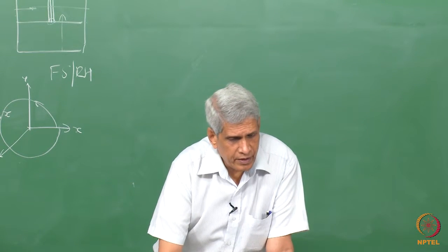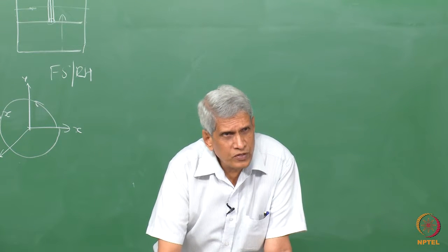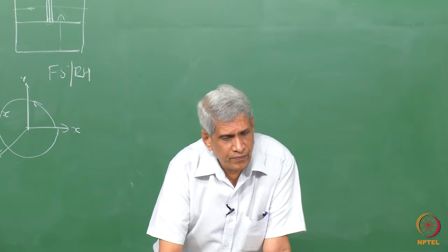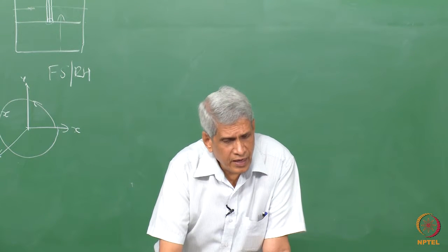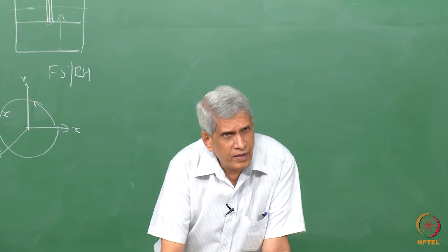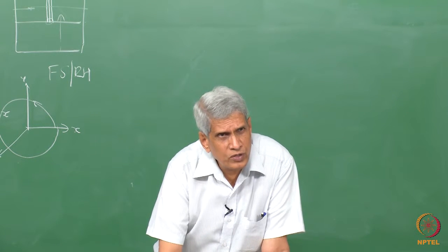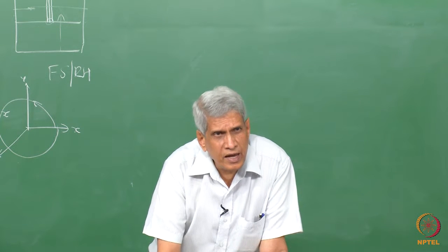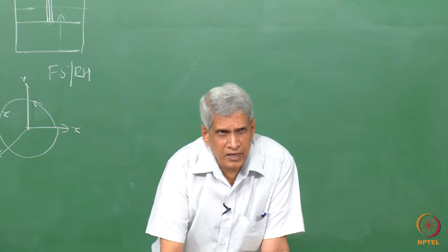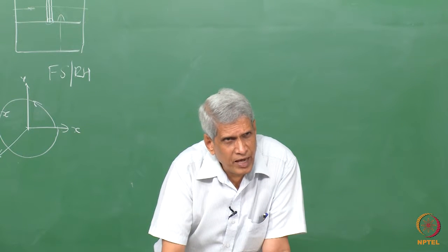That is essentially what we have taken here. What we have done is that we first do a Burgers circuit around the dislocation, and then take a region which doesn't contain any dislocation, do a similar procedure and find out the gap, and in which direction, and the magnitude of the gap.